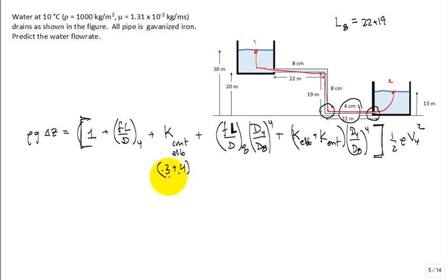People try to avoid them. Usually you just have inlet, outlet, and then put a reduction on it, a contraction on it. So if you did it that way, which is probably the way it would go, you would put a contraction of 0.4 here. And then on the elbows, how many elbows do we have? We have 2 elbows, 2 times K elbows. That makes more sense. Okay.